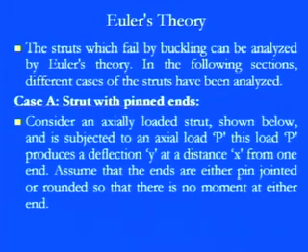So here we have the strut with pin ends at the extreme ends of the strut. Consider an axially loaded strut. The loading is simply axial, along the longitudinal direction shown in the next figure, and it is subjected to an axial load P. This load P produces a deflection. Obviously, when you apply the load along the particular axis, we get a deflection which can be measured as y, at a distance x from the end.